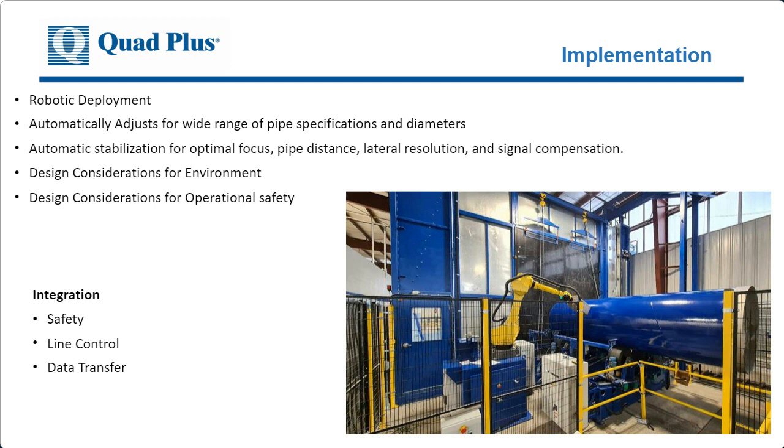But we also use, to measure where the pipe is, 3 lasers next to our sensor that measure the distance to the pipe. And we put the sensor on a 100 millimeter linear slide as well, so that we can auto focus the sensor to try to keep it in focus, at optimal amplitude and a set distance from the pipe.